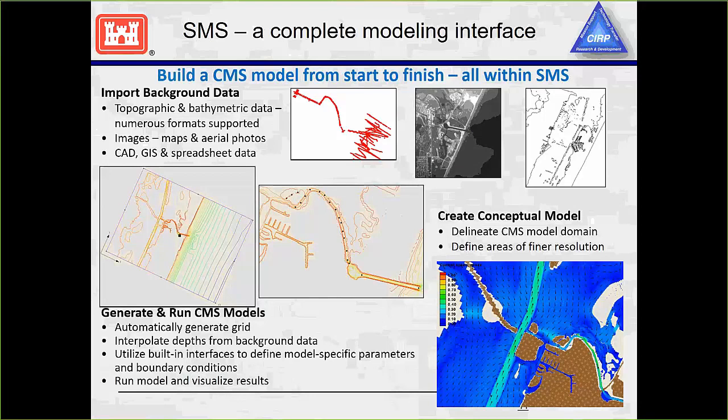So that's from taking in profile lines and making them into bathymetry points. You can load in aerial photos for visually locating your area, or when you're making a report type plot for a customer, they can easily see where they are. You can start with initial coastline arcs. Then we'll build a 2D grid frame, import all the data and bathymetry, and it'll look something like this. And then we can go in and add resolution, different things. We'll be showing that throughout today and tomorrow.